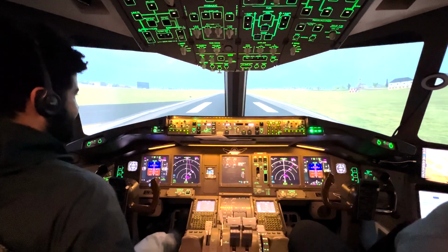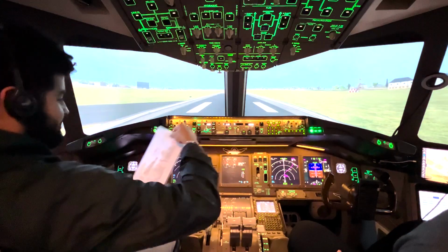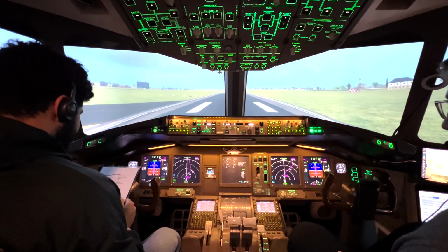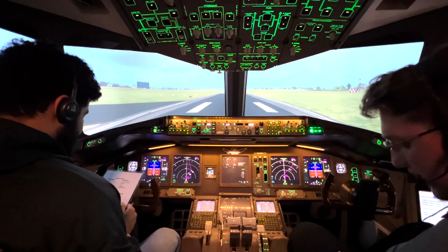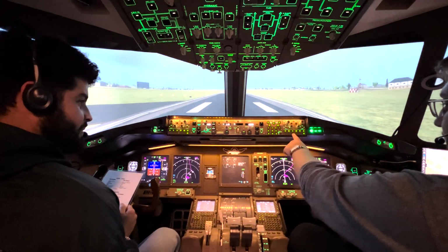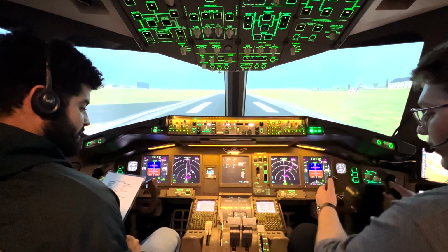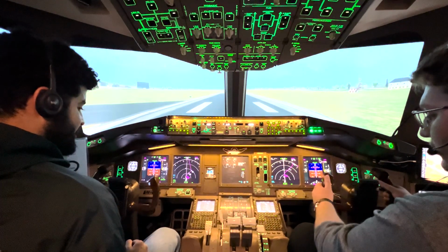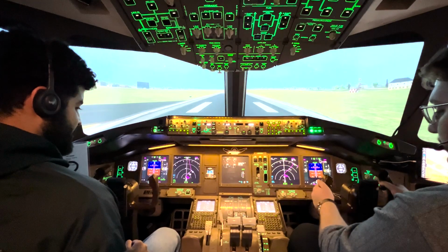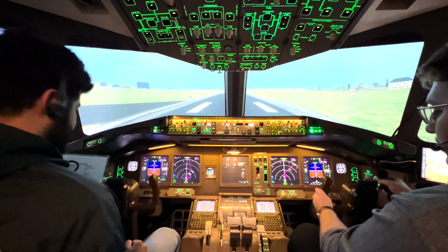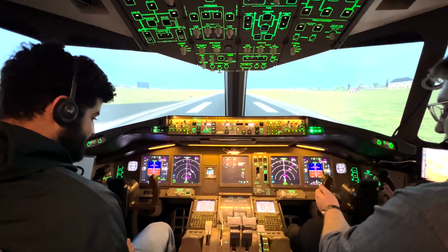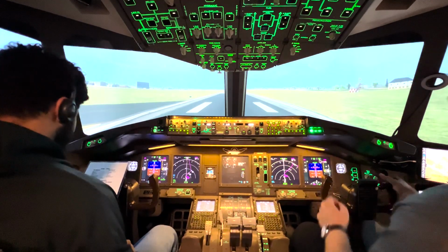There you go. Okay, so before takeoff checklist, please. Flaps. 5 in green. Transponders. TCAS, TA/RA, and auto. Flight controls. Okay, that's a good one. We have to check the flight controls. So see here, we're going to do full up, just like that. Neutral, full down, neutral, full left, neutral, full right, neutral, and full rudder left, neutral, full rudder right, neutral. Perfect. Flight controls free and correct.